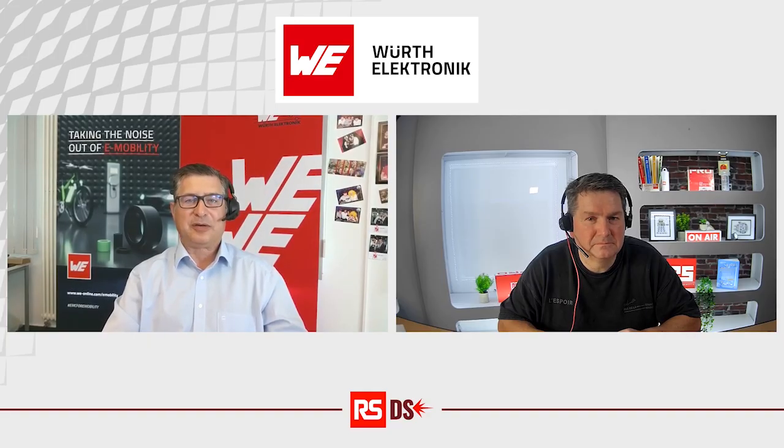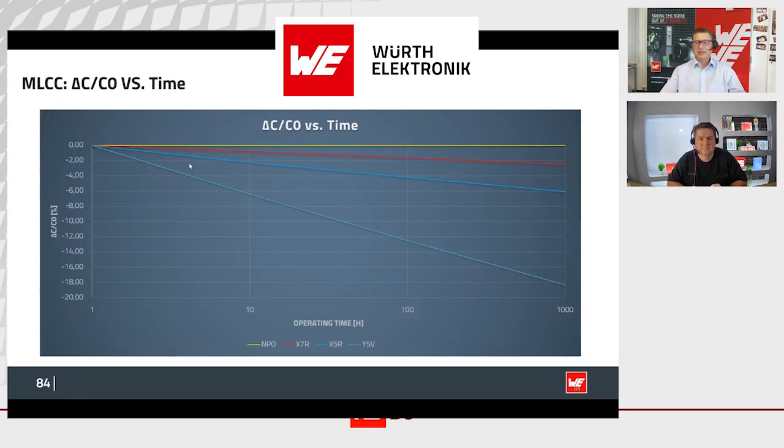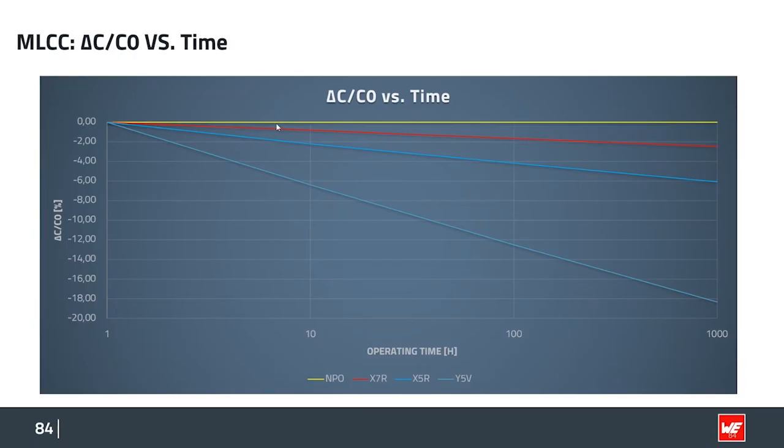Then I talked to our product manager for MLCC. He said, hey, yeah, we know that, and showed me some pictures of what happens to MLCC over time. This is NP0. They are very stable. You get something for the money. NP0 is not expensive just because it's nice to be expensive. It's because it has a very, very clean dielectric and excellent behavior.